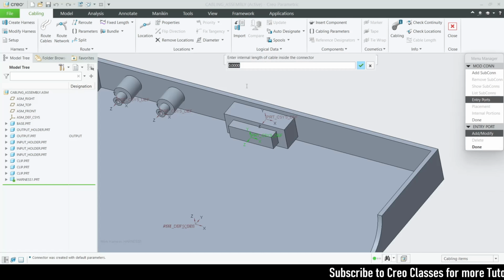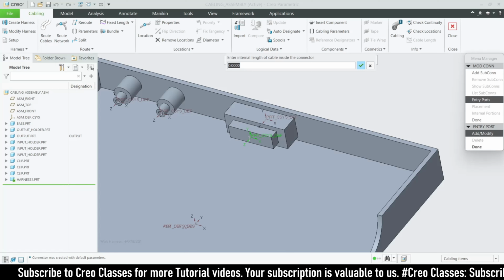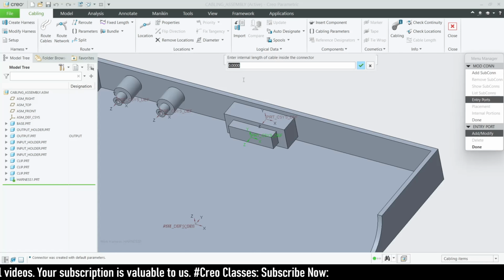I'm going to click OK, and a pop-up window shows up: enter internal length of the cable. As you can see, this coordinate system is placed on the top face of the part. If you create a cable, it will be created outside the surface, so to turn it inside, we have to adjust some internal length for the cable. Here I'm going to add a minimum value, 0.2. Then you can click OK.